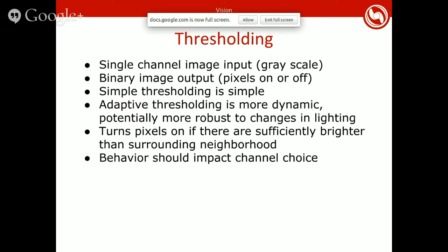So we have this grayscale image that has, let's say, if we're looking for an orange path, some rectangular-looking, either really gray or really dark object that stands out from its background. And then when we threshold, ideally what we want is the image is all black, except for a white rectangle somewhere on the screen, which will be our path segment.